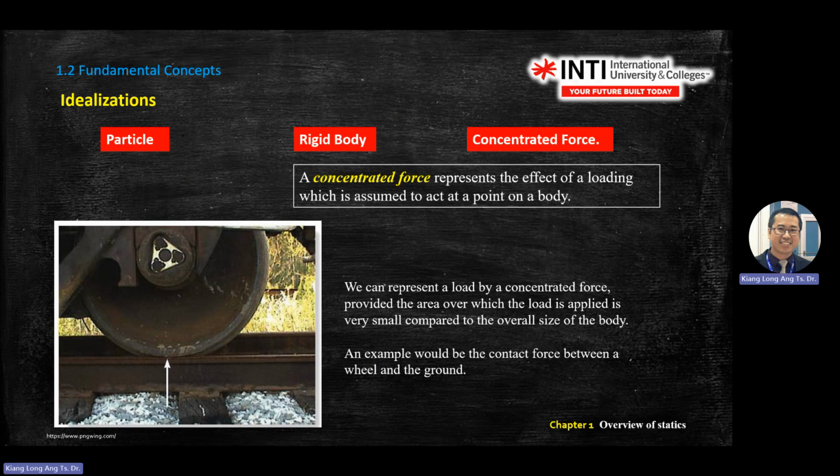Okay. So when you do a rigid body free body diagram, you need to label what points you're focusing on, what locations you focus on. These are the careless mistakes usually in the question: you draw the wrong free body diagram, you put the wrong location of the force, or some force is missing. Basically there are three idealizations. You see the question as particles, you see the question as rigid body, and then you solve concentrated force on the particles and rigid bodies.